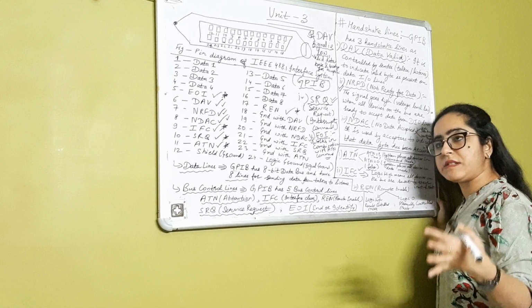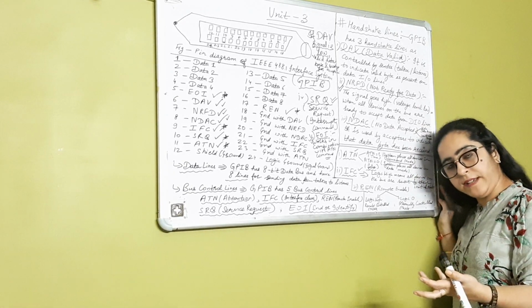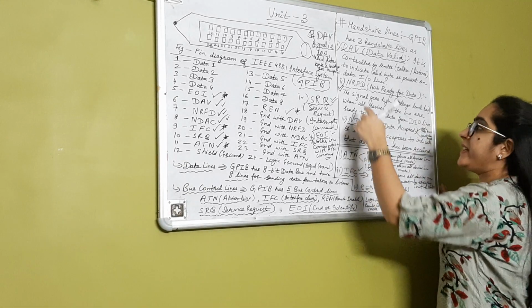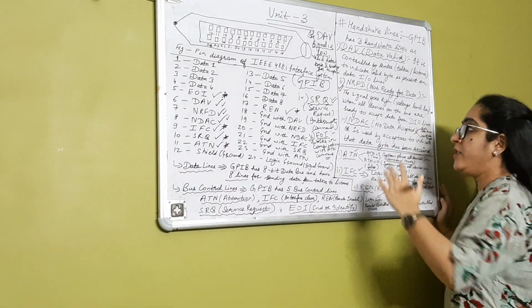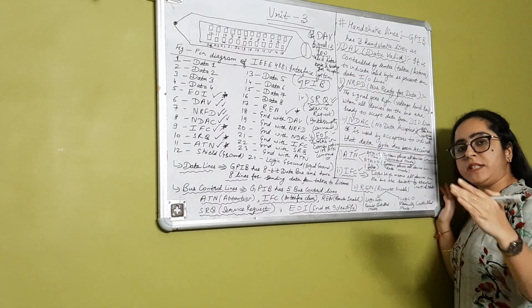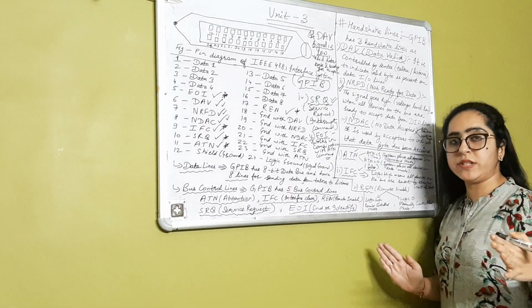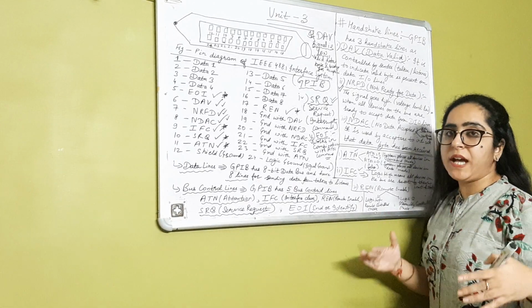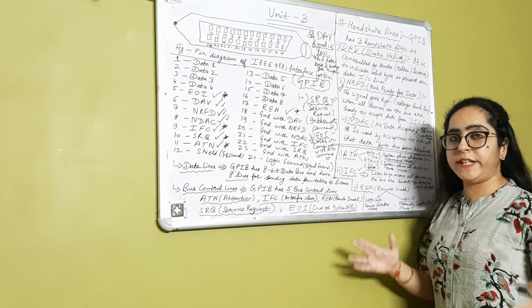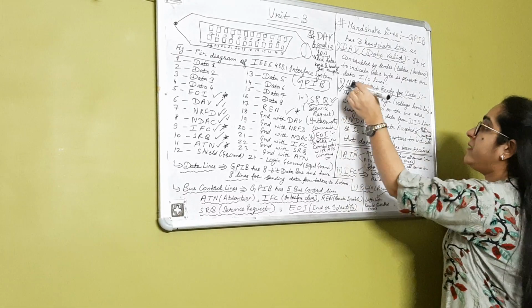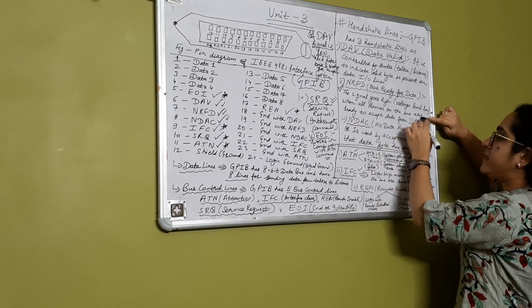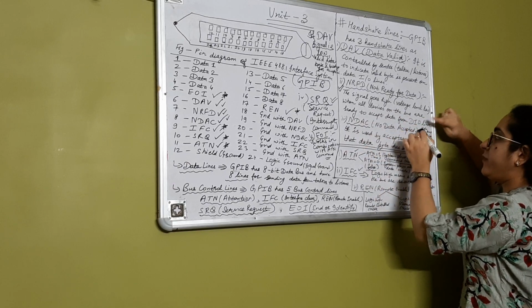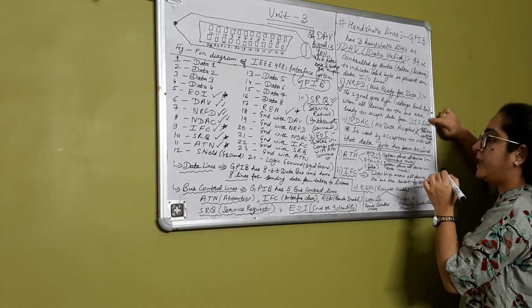If some of the listeners were executing the previous instruction, in that case NRFD will go low because all the devices are not yet ready. When all the devices are ready and the previous instruction is performed, then the NRFD signal goes high. Okay, when all the devices on the bus are ready to accept the data from the data input output lines.